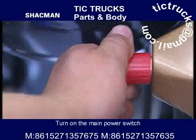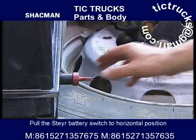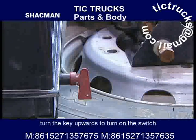Turn on the main power switch. Pull the steer battery switch to horizontal position. As for main battery, turn the key upwards to turn on the switch.